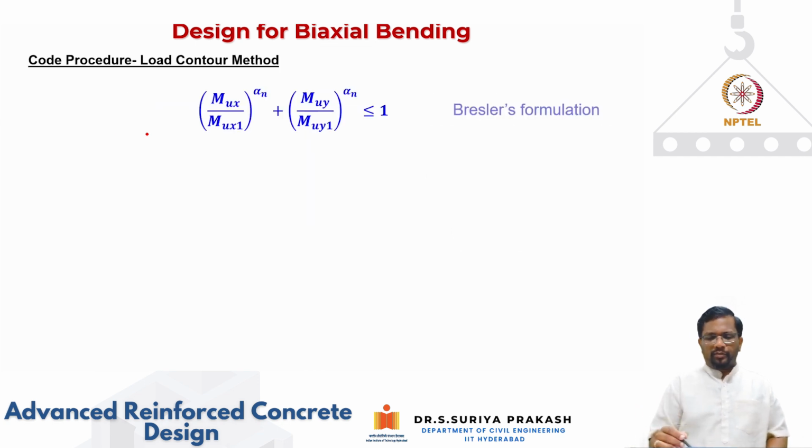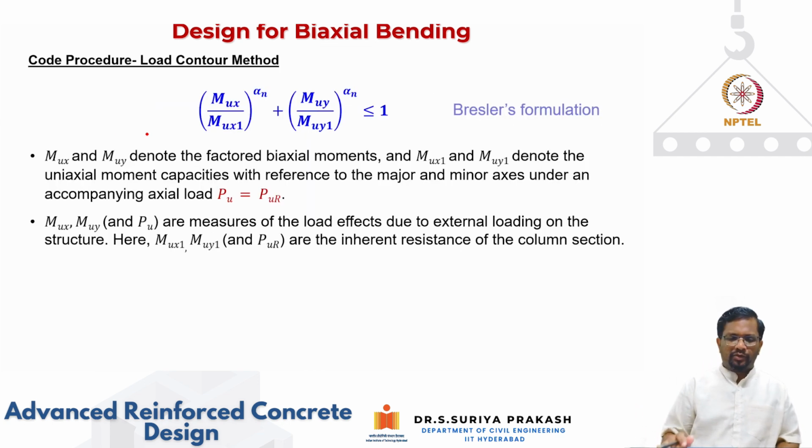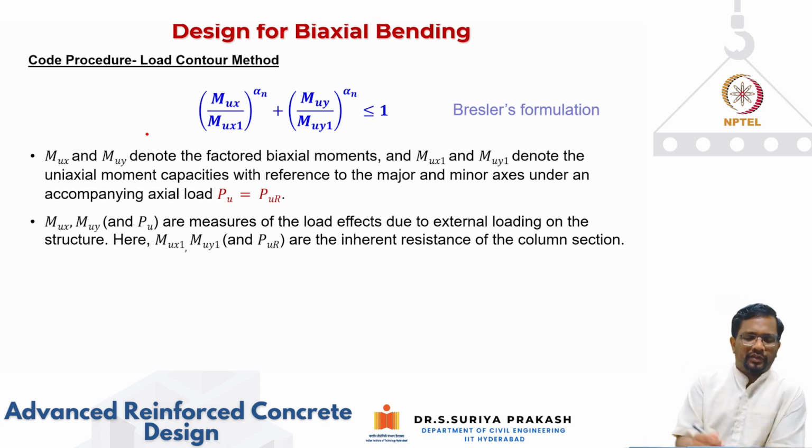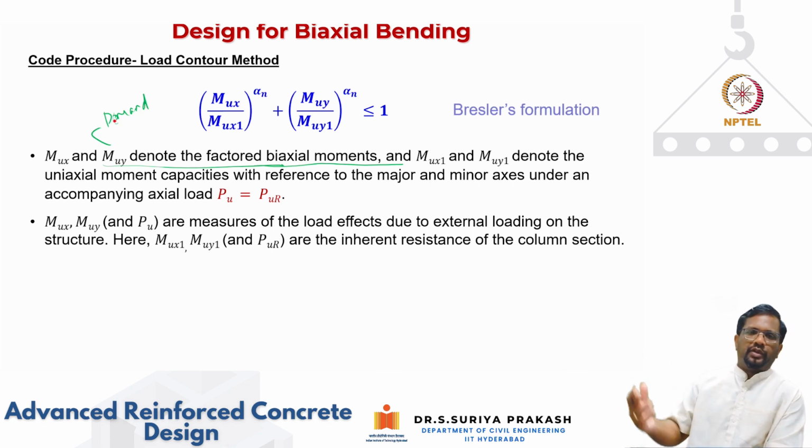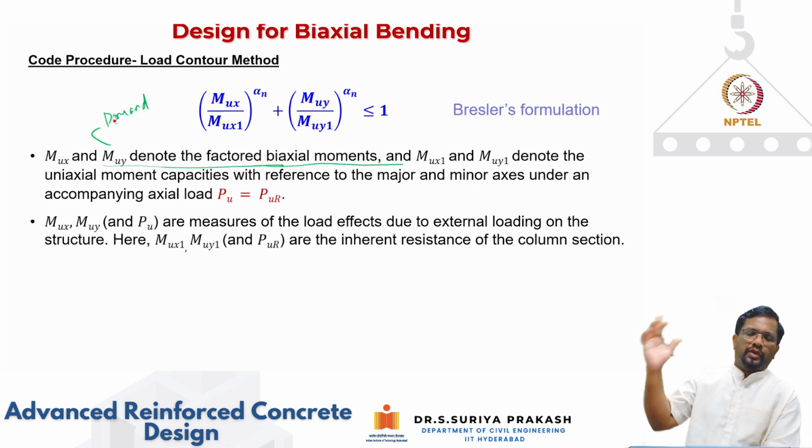Now, this is the Bresler formulation. Let us see what MUX and MUY are. We have already discussed that MUX and MUY are factored biaxial moments. These are your demand. These are your demands from your analysis.